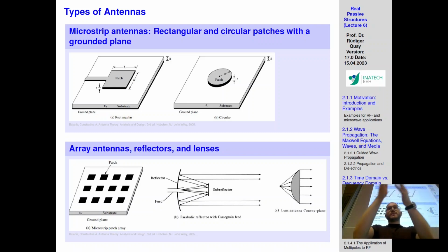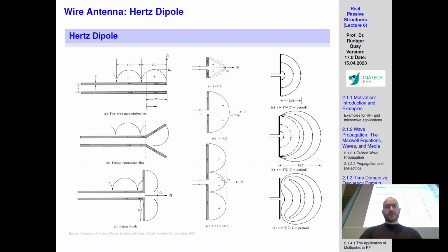Adding more of these patch antennas together, you form an array, and these arrays, due to additive layering of the radiated waves, constructive interference, dependent on the distancing from each other, can create a singular radiation pattern, and also help in expanding the aperture. That means the aperture becomes bigger, and your focusing or directivity becomes narrower and higher. You can reach larger distances. For that, you can also use cascade antennas, as seen here, or you can also use a lens. Later on, we'll show examples.